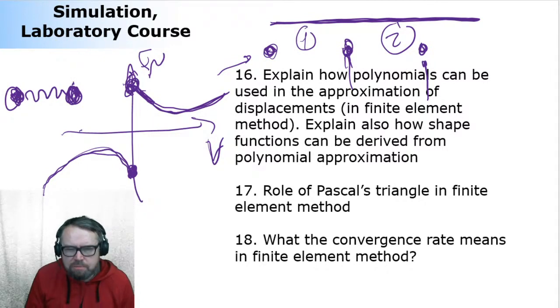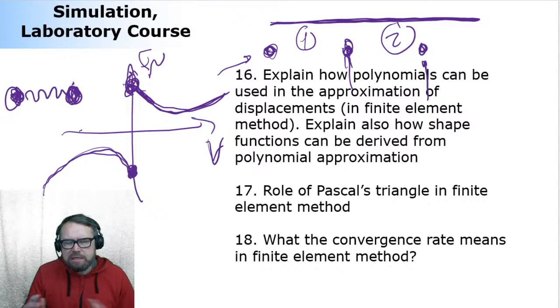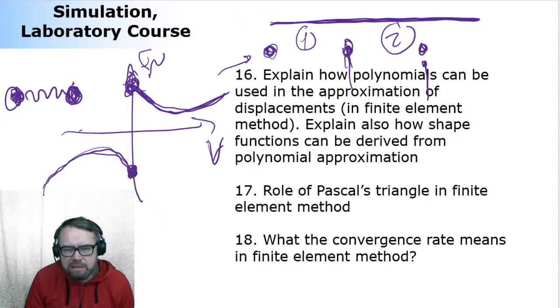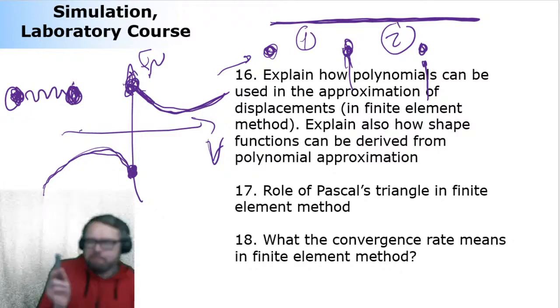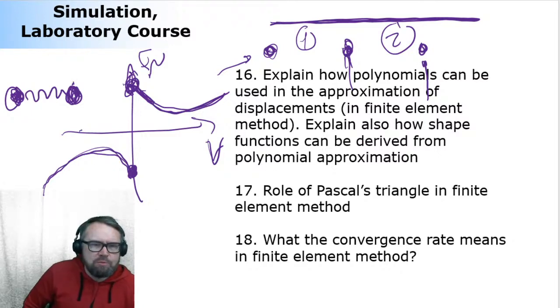For sure, this kind of jumps can also be considered a source of numerically stiff problems, because then there is an infinitely high frequency related to this jump, and this infinitely high frequency confuses the integrators, and they will have a really hard time dealing with that. I'm sorry that I'm jumping from one topic to another like that, but for some reason I missed a part of the comment earlier, so now I saw that there was this sine function involved as well.